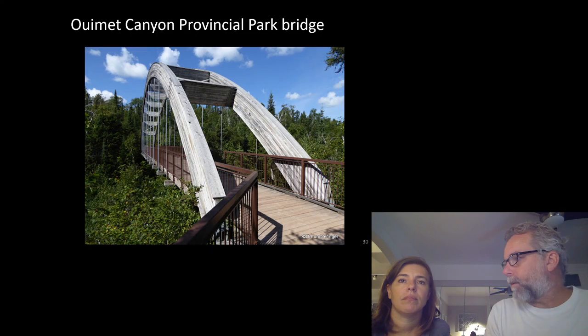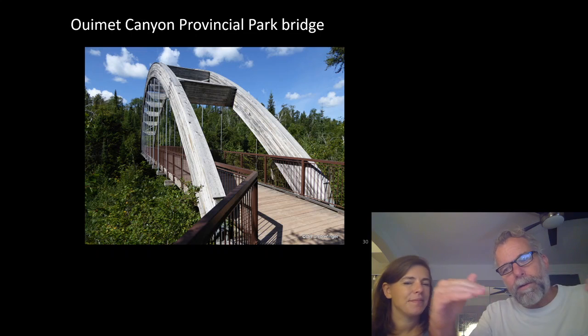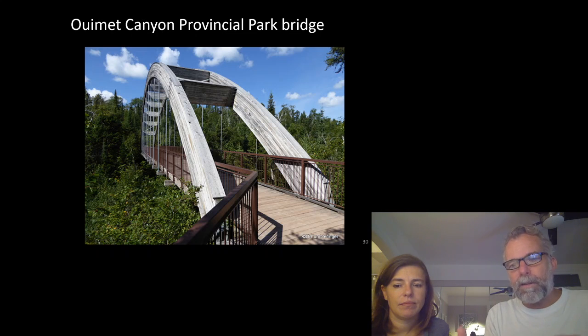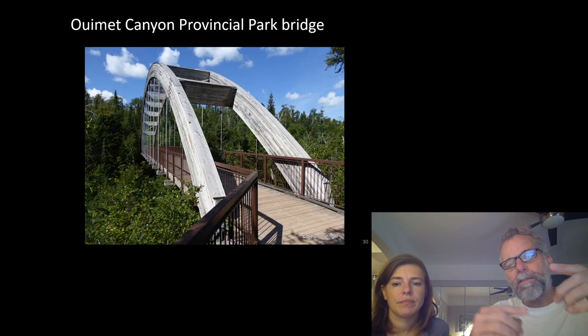An arch is a funicular form, so we started talking about the funicular catenary and its need to deform to resist the varying load conditions. In an arch, we have a funicular form, but it's deep, and so it's bending stiff. So we have two superimposed load-resisting mechanisms.